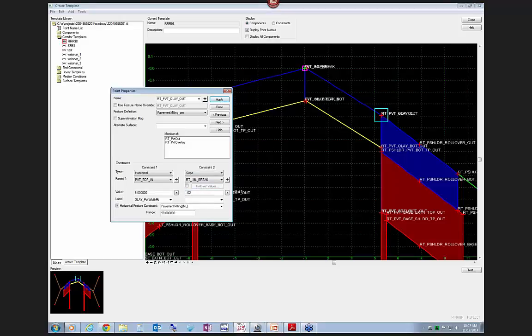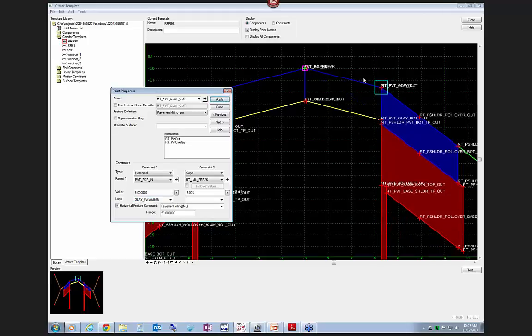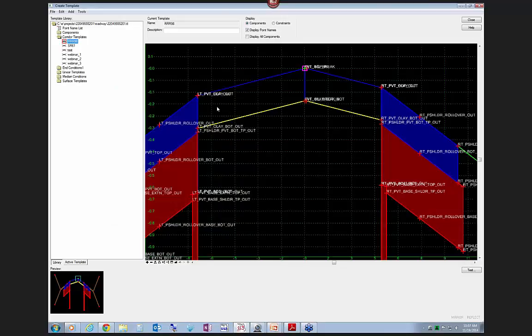and then you would set like a minus 0.02 or a 2% slope, and what will happen is it will build this overlay in at the slope that it's set to, and then the overbuild and the milling will adjust according to what this overlay needs to be. The overlay thickness is still going to be the same. If it has to put in overbuild, it will. If it has to mill down farther than a normal slope, then it will, and it actually creates your variable depth milling that way with a cross slope correction.